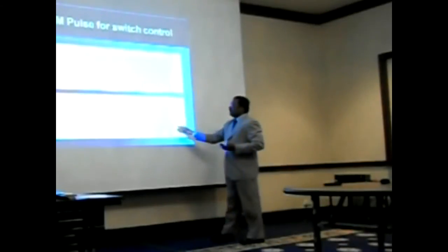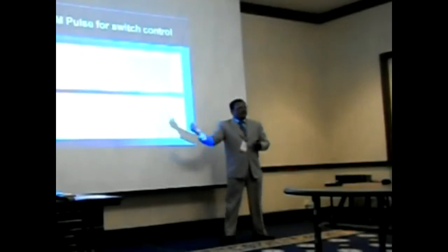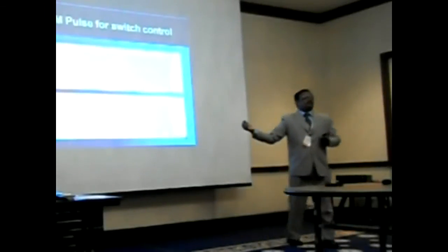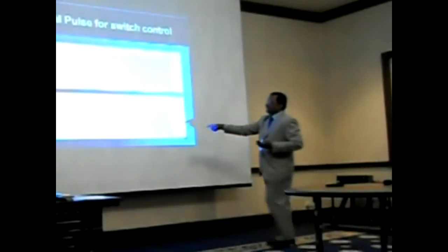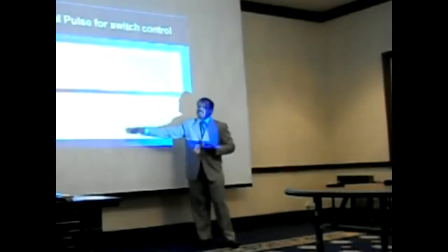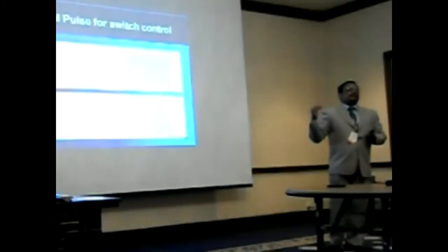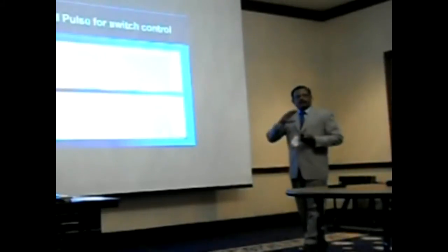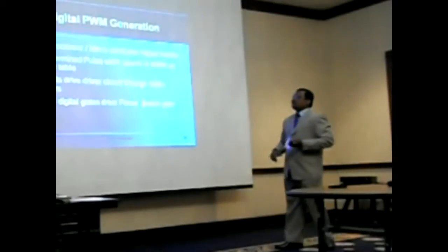In the proposed raised sine wave, you can compare these two, the initial pulse width is less till about 10 degrees. And the peak in the center is the same, so there is no difference in the peak value that you attain. Only in the zero crossing area, the width is slightly reduced by using the raised sine wave as a modulating signal.